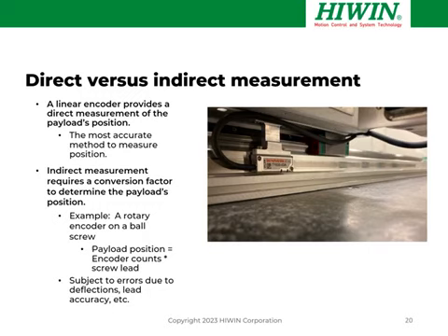An absolute encoder, on the other hand, provides a direct reading of the position. It outputs a digital word using a protocol. Homing isn't needed. The encoder knows exactly where it is immediately upon power up. Common terms you might hear when people talk about absolute encoders are EnDat encoder or BiSS encoder. These are actually describing the protocol used. So it's important to verify that the drive that you're selecting, the servo drive, supports the encoder protocol to ensure compatibility, make sure they can communicate with each other.